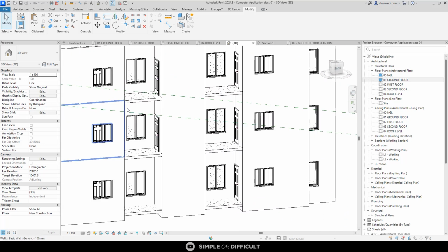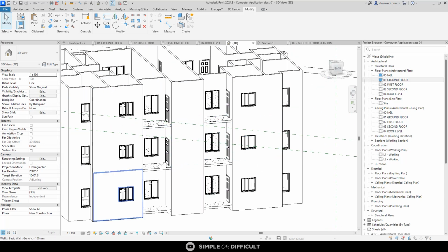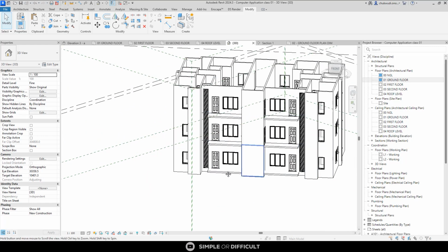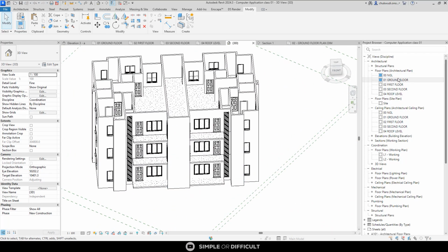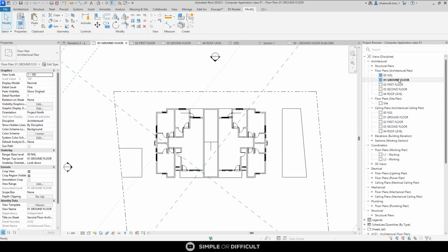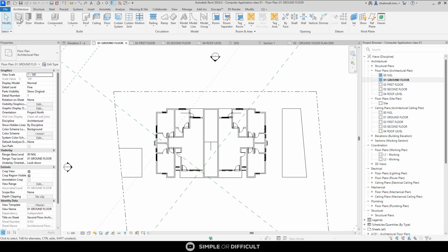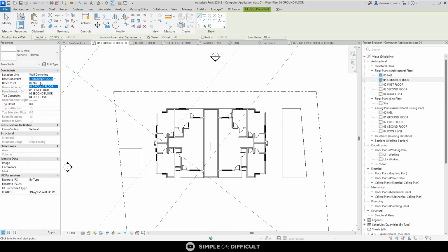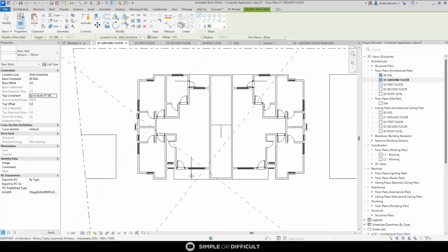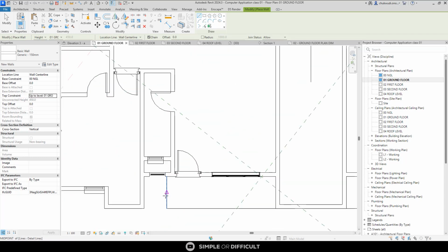And then underneath here, we need to add a 300 beam, that is going to be 150 because 150 is also going to be embedded in this floor slab. So 150 is going to drop at each level. So we're going to just be doing that with a floor. So how do I do that? I go to the ground floor plan and I select a wall. In this wall, I'm going to set the base to be NGL and then the top to be ground floor, right?